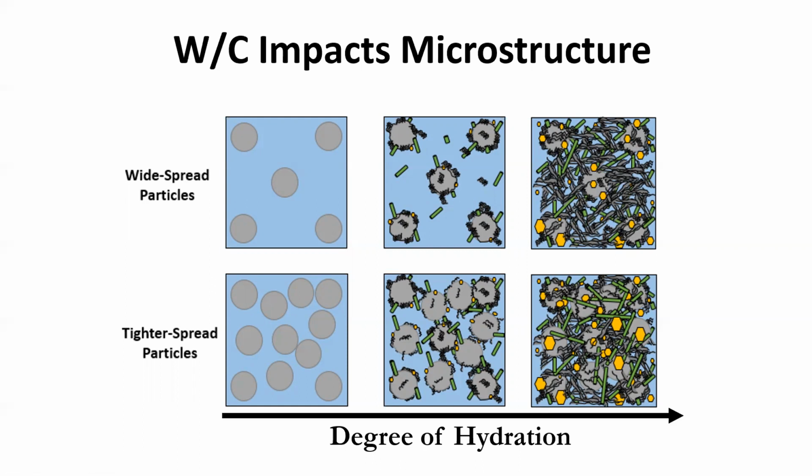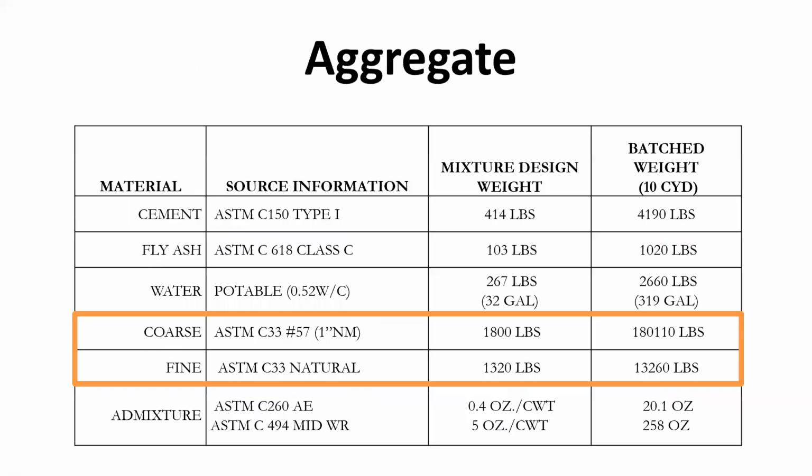And then over time, your strengths are just going to be weaker because it takes a lot more to extend to get that bond from the cement particles. And if you have a tighter bond, like you see here, it's going to be easier to bridge to get to these cement particles, and you'll have a much tighter matrix, a much tighter pore structure of your concrete.